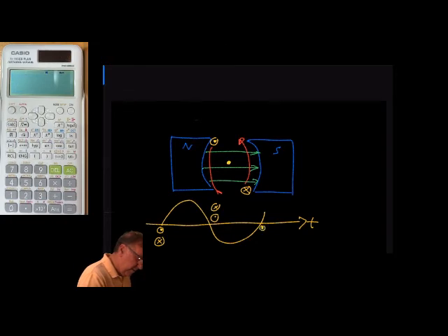So we'd have this configuration of our rotor within the magnetic field, which is saying that if the rotor is aligned this way, you're not cutting any of the magnetic lines of flux, so no voltage is created. When it's horizontal, you are cutting across a lot of lines of flux. So that's where you would have either a maximum here. Actually there's 2 maximums. There's a positive maximum and a negative maximum.